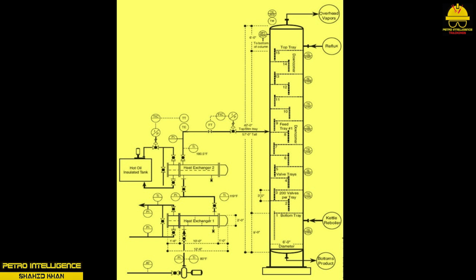By knowing the boiling points of the different components in the feed mixture, an operator could determine the approximate material composition and the place on the tower each component will exit. Heat balance operates under the same principle as material balance. What goes in must come out and must be maintained in order to hold the heat balance.